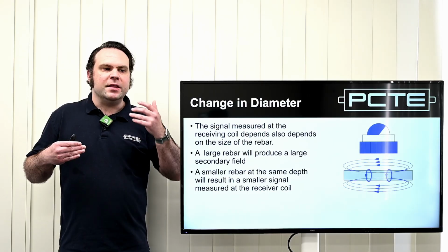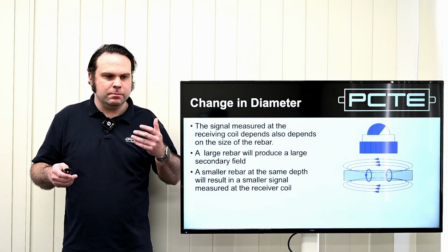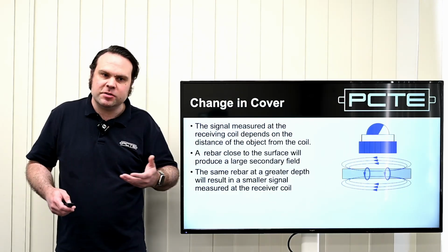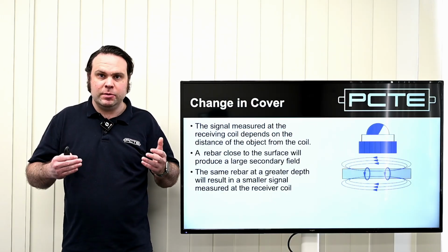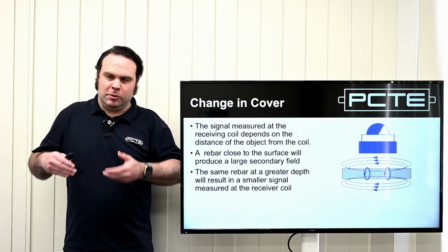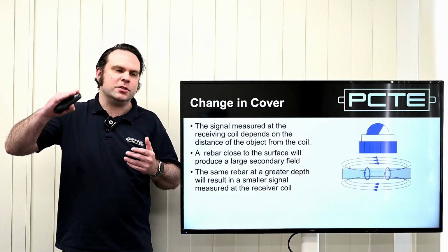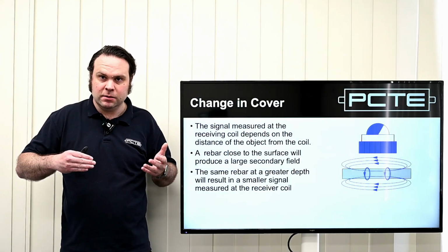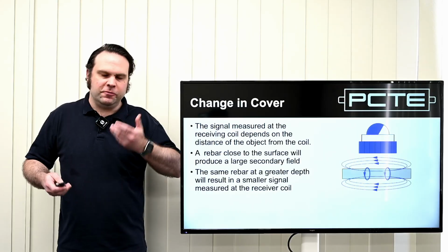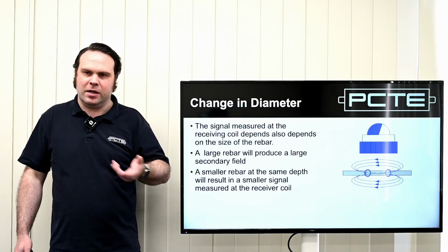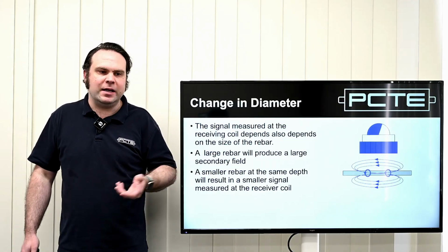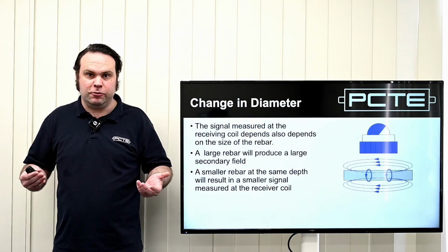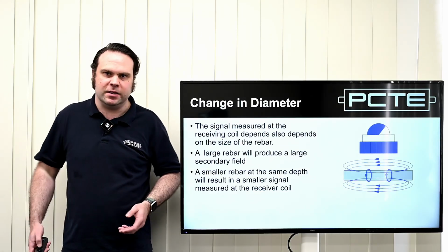But the diameter estimate function, because of the very small change on the test and some of the interference issues I'll discuss later, it's an estimate and it may fail. So it will either give a reasonable value that's not very precise and shouldn't be used for things like strength analysis, or the device is going to not perform. It'll tell you it can't do it, or it'll tell you it can't do it indirectly by giving you a ridiculous number. So do watch out for that diameter estimate function. It's appropriate in some cases, but it's a very limited functionality.